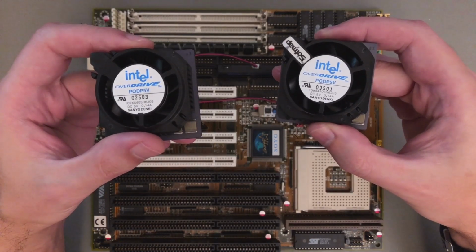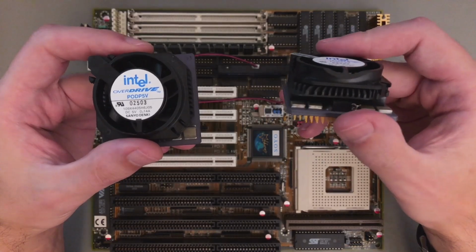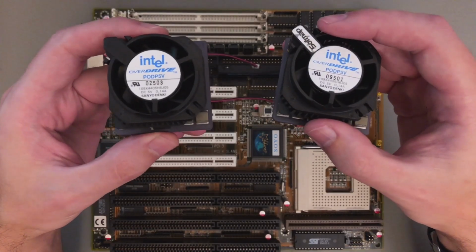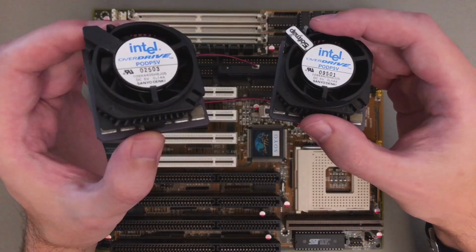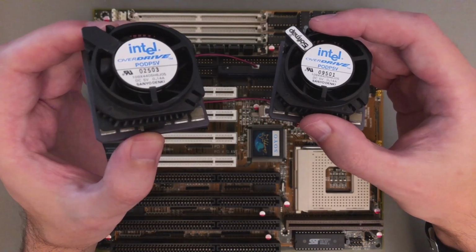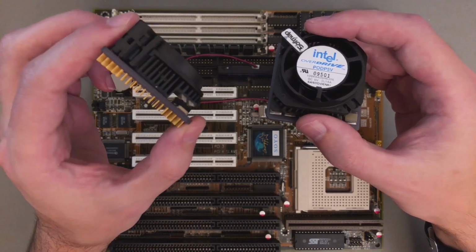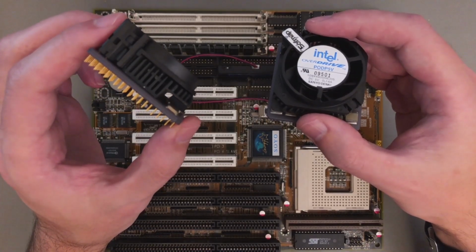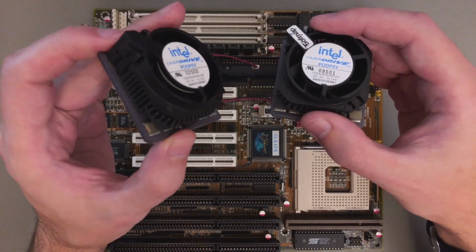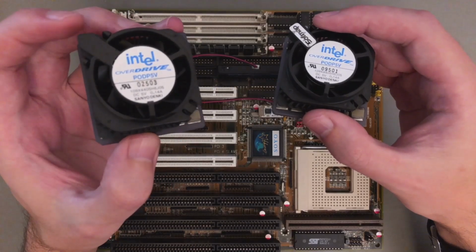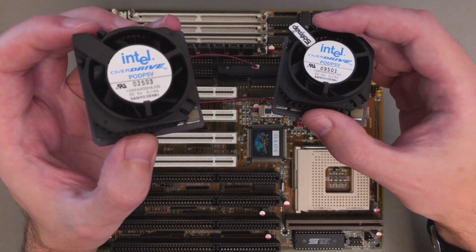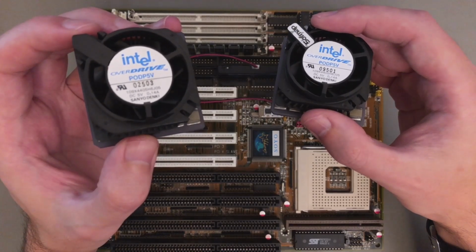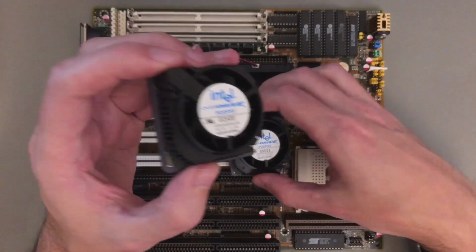Well, actually I have two more of these, but the other two are on the operating table and you will see them later. And here is the voltage regulator, and on the top there is this specially engineered cooler. First of all, you have this cutout here for the voltage regulator. Secondly, it communicates with the CPU, and if this is not plugged, the CPU deactivates the 2.5 multiplier and just works in 1x mode.